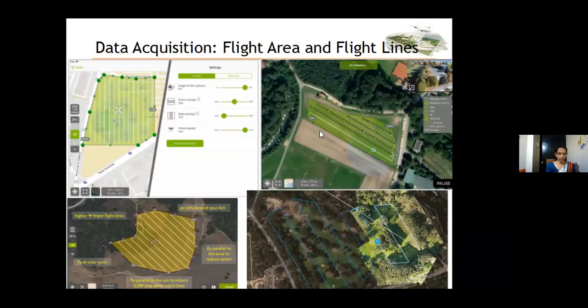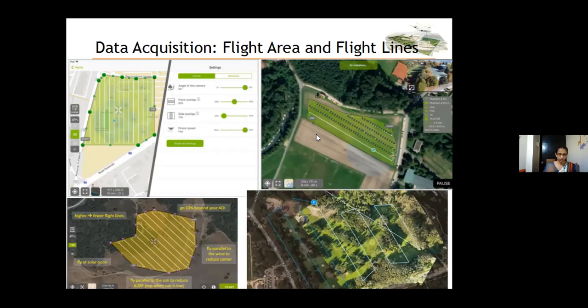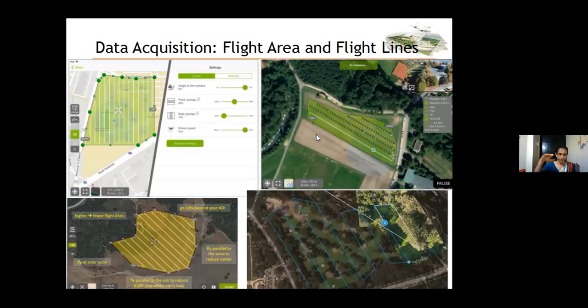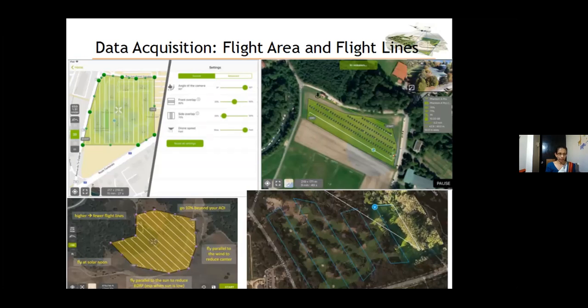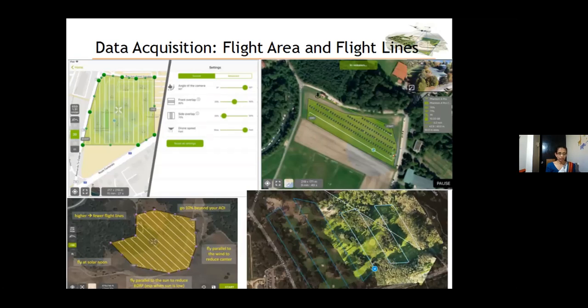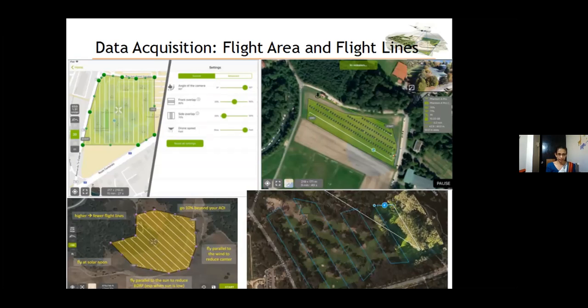There are other modes also, like fly by wire, that reduce rolling effect in the left-right direction, so it will maintain the stability of the flight. You can also use a fully autonomous flight mode, or an auto landing option, so you do not worry about the landing process. The drone can hold the altitude with altitude hold options. So there are very high level commands available in today's UAV systems.